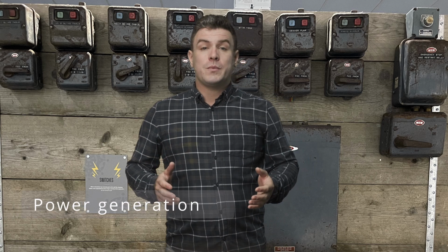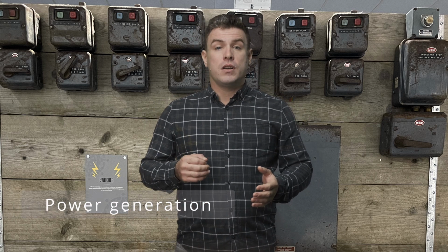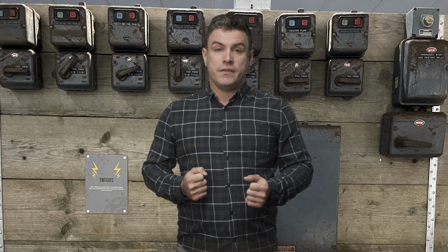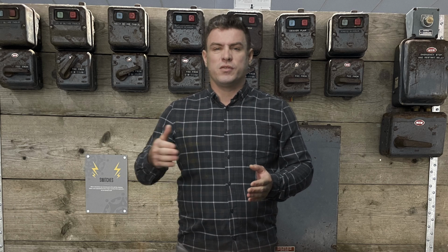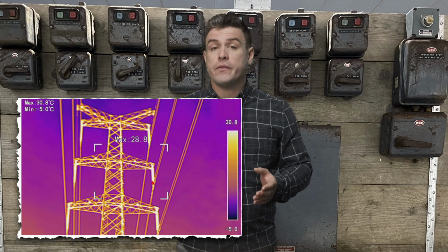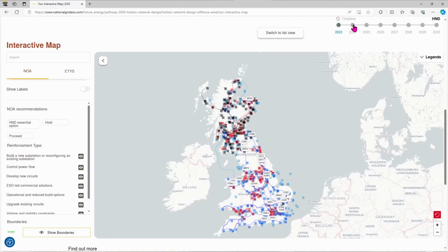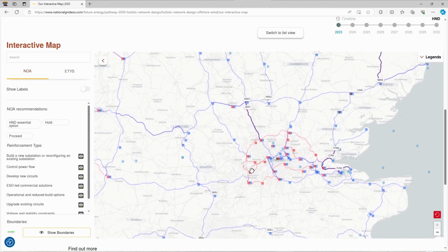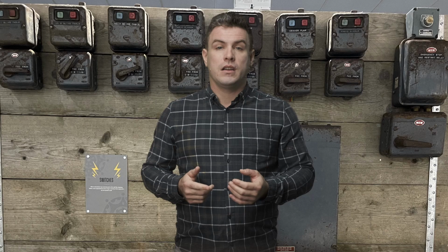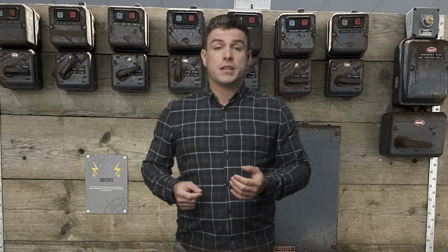I learned this week about power generation and how a large voltage is used by the national grid. This is to reduce the voltage drop, which ultimately would become heat. According to the information, there's nearly 5,000 miles of overhead and underground power lines linking power stations together and interconnected through the country. That's pretty impressive. The interconnection means that if there's an issue, power can be transmitted through other lines. A lot of the electricity is transmitted with overhead lines. The material gave me some reasons why this is chosen. These steel cored aluminium conductors.